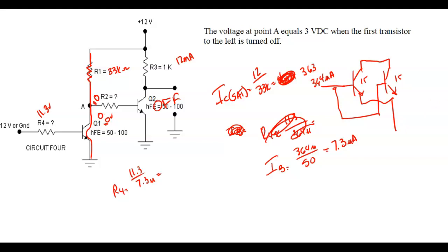Very seldom in series. But so we can look at some power amps. I think I got a diagram of some power amps, and they have several of them hooked in parallel. They put a little feedback resistor in the base, in the emitter, to keep one from taking the load. Oh yeah, this is the name of the game.